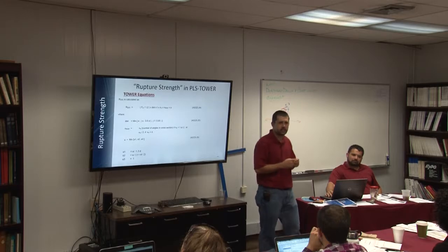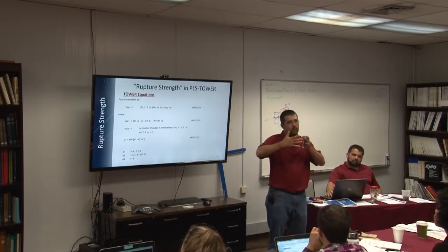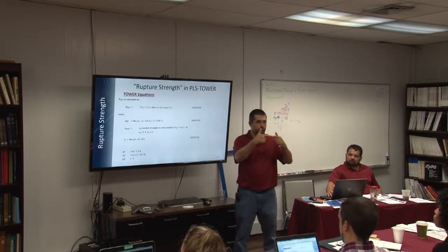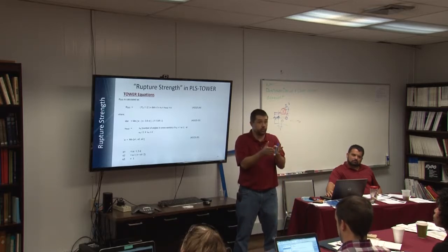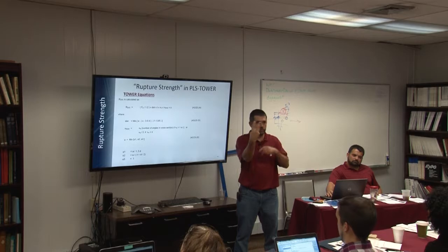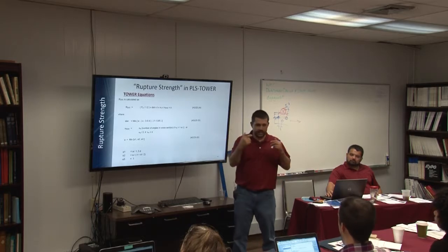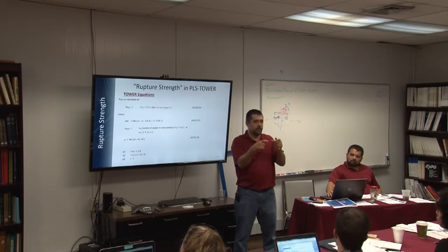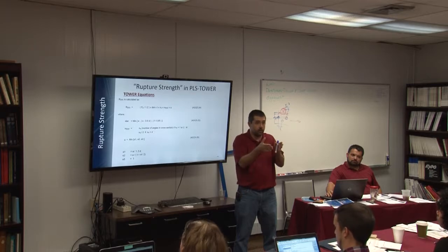Yeah, it's kind of like bolt shear, essentially. So if I had a double angle, basically in bolt shear, if I had one bolt in double shear, there's 2 shear planes. So the number of shear planes would be 2. Here, in that same case, that bolt is going to have bearing on 2 different pieces of that member, of that double angle.